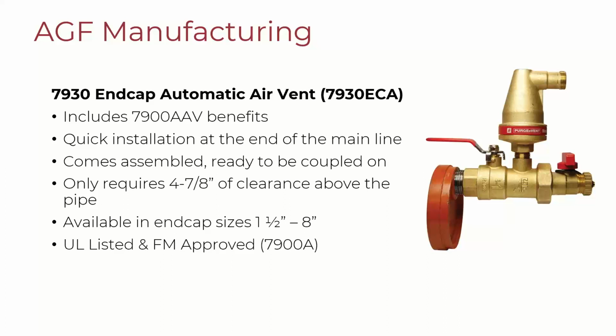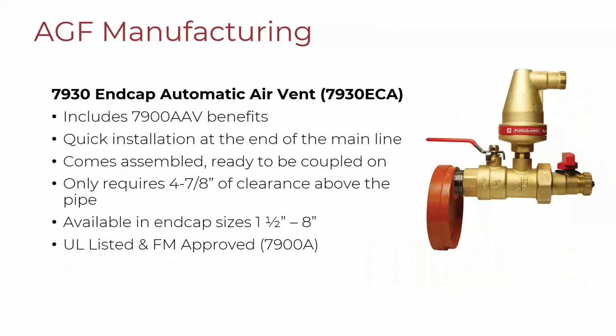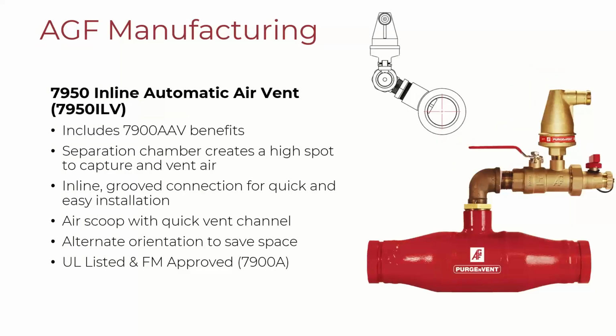Like I've said, it's essential that air vents be installed in a vertical format. So we were challenged with making a unit that would fit, especially on ESFR, large distribution warehouse systems. They were the ones that said we had to keep it in a very tight footprint. So by having that installation methodology, we can fit in under 5 inches of space in height.